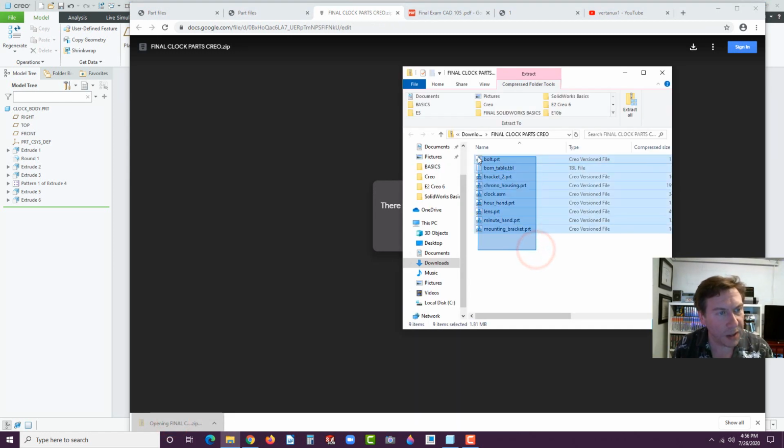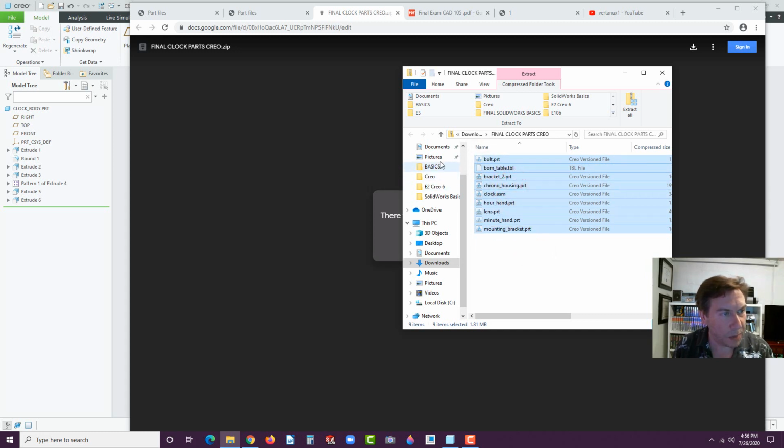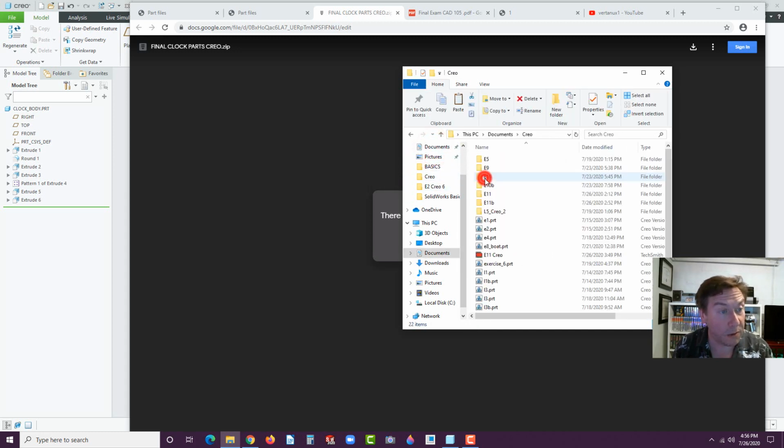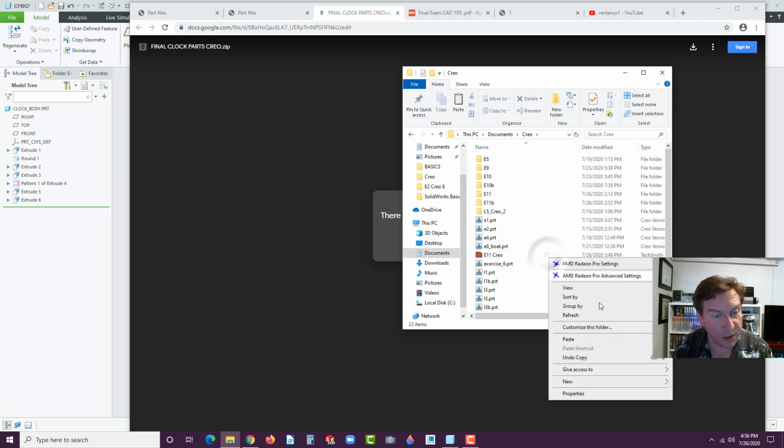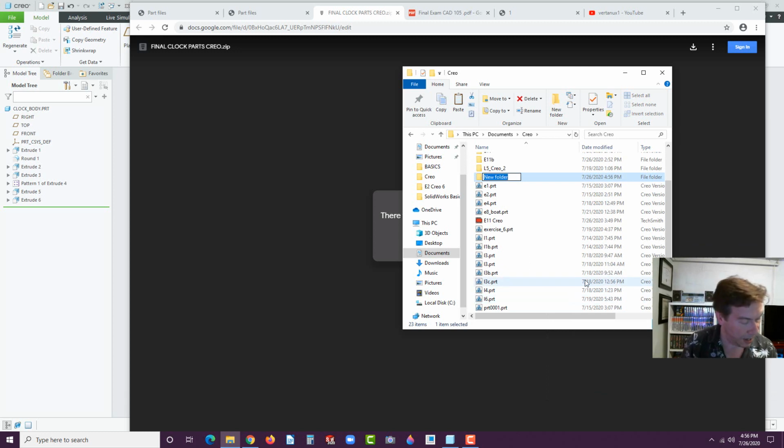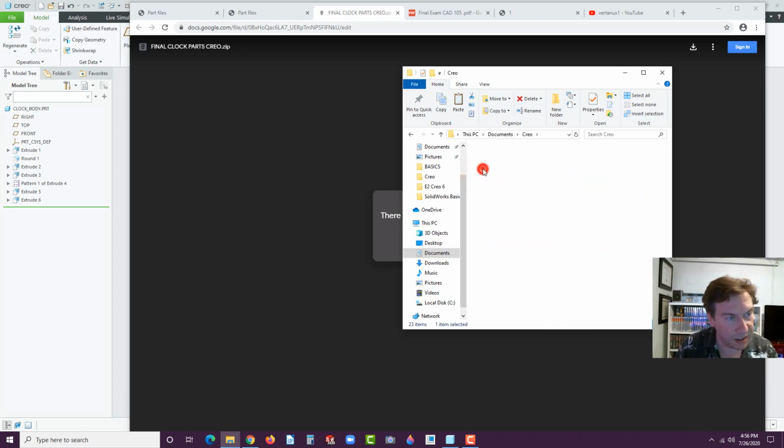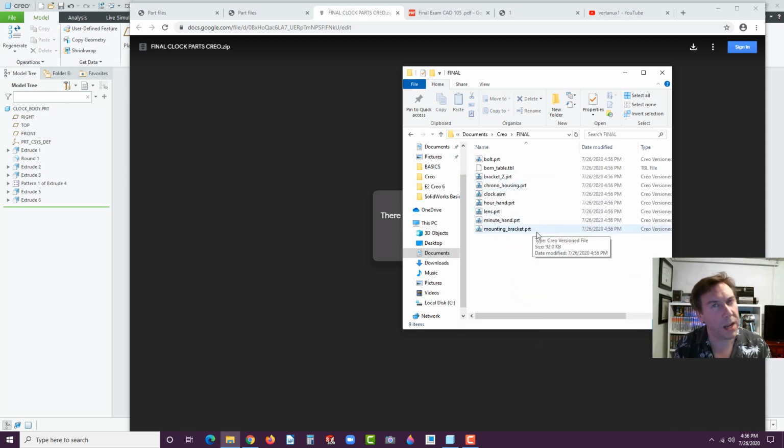I'm going to click on that. I'm going to select them all, right click, cut, and I'm going to drop them in on my documents. I have a Creo folder that we've been using all semester. Right click anywhere here, go to new folder and call it final. Double click on it, double click on it again, right click, paste. Now the BOM table may not be functioning yet. I still have to update that. So we'll just do it manually.